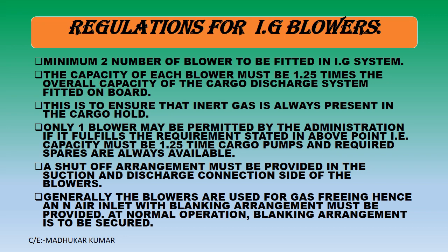Generally, the blowers are used for the gas freeing, hence an air inlet with blanking arrangement must be provided at normal operation. Blanking arrangement also is to be secured.